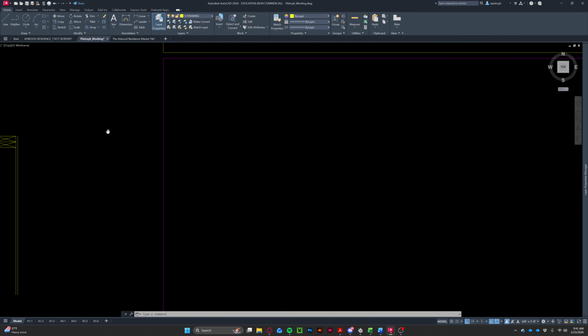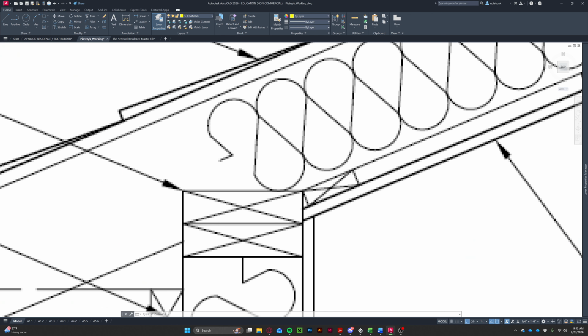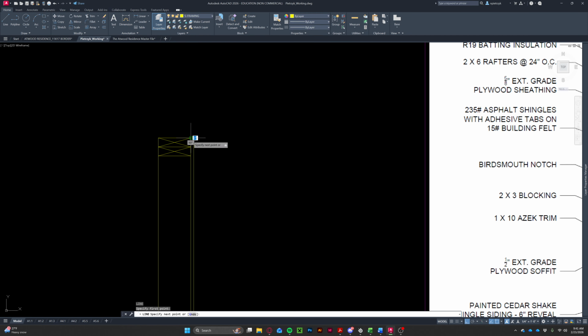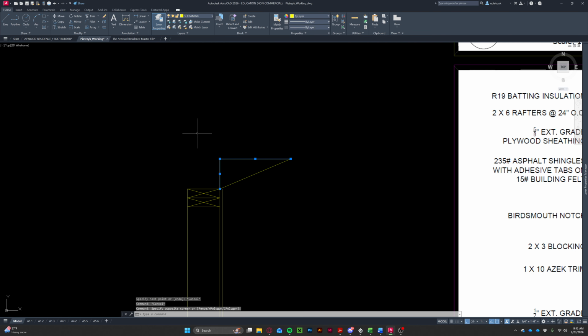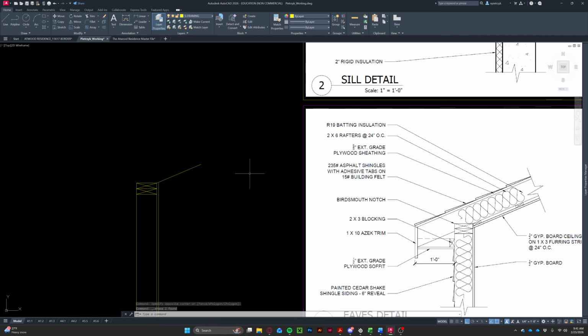And also I can see from here that this bird's mouth, this cut that occurs on this wood here, starts at the very corner here. So very simply, I'm going to go up 5 inches and over 12 inches from this side. Draw a line to connect the pieces. Wouldn't you know it, I got the angle all set up.